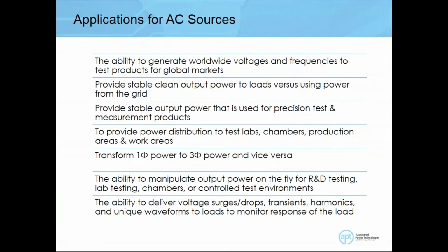Now, a lot of the labs also have what we call test chambers that need to have Energy Star testing. In Energy Star testing, you're required to have a particular amount of voltage applied for a significant amount of time. So not having any disturbances on this voltage application is really important. You want to make sure that any source you are sourcing out has this capability of doing clean and regulated power.